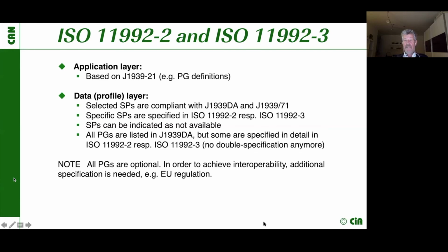was regarding the time and date parameter group. By accident, somebody has swapped day and month, because you know that American people have a different order of this than the European ones. And so it happens that some implementers have first the month and second the day, and other implementers have first the day and then the month. So that means they are only correct on 12 days per year: the 1st of January, the 2nd of February, 3rd of March, and so on. So you have to be very careful with this. If you see an implementation, then you have to look at what they have really implemented.